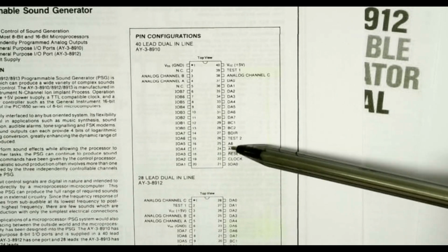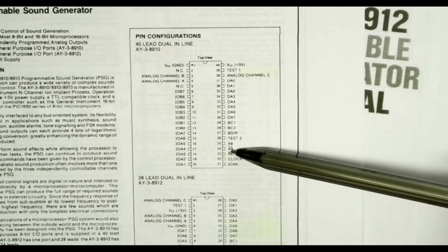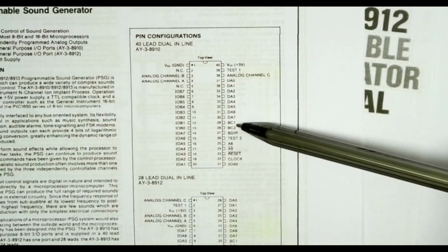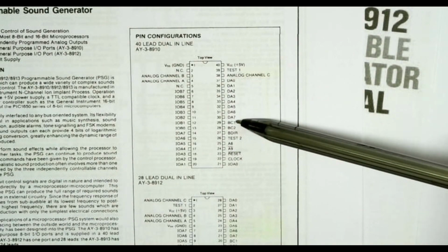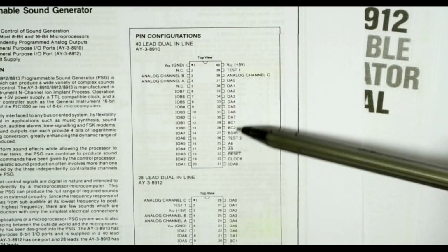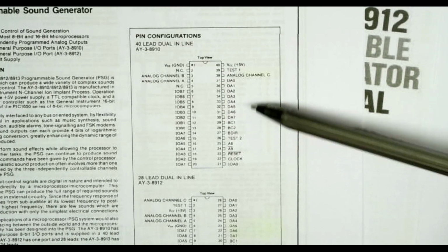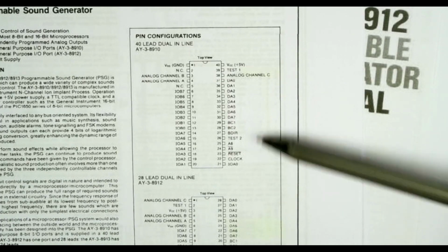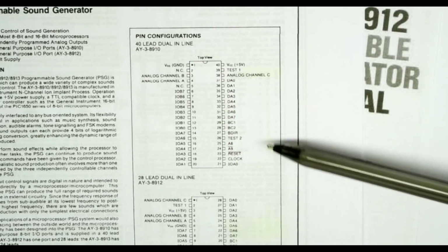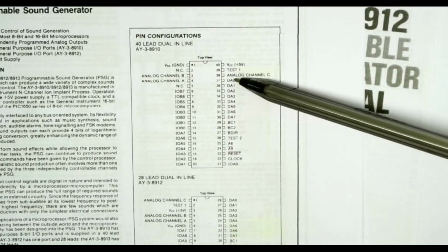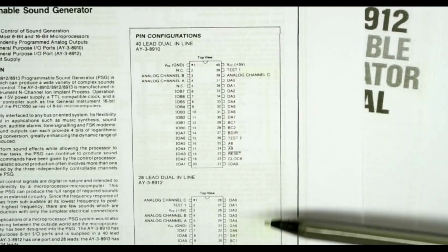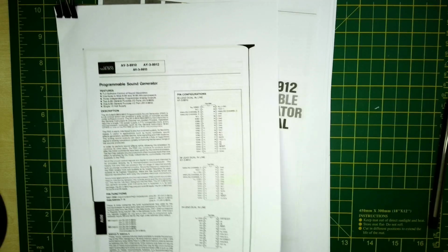We need a clock. These are some of the address line and chip select signals, and it has a slightly unusual decoding from the CPU in that it uses BC1, BC2 and BDIR, which I think was compatible with the General Instrument CP1600 chip this was designed to use. So it's a 40-pin chip. There are a couple of pins which are not connected in the test, things we shouldn't be using, but mainly we're going to be needing to access the data lines, the bus control information and the outputs from there.